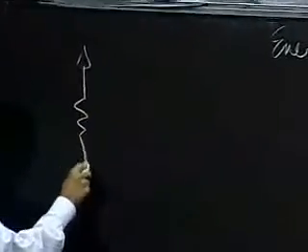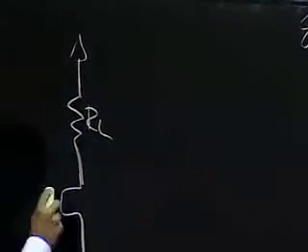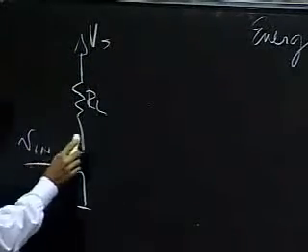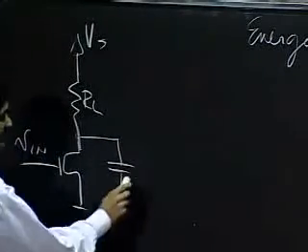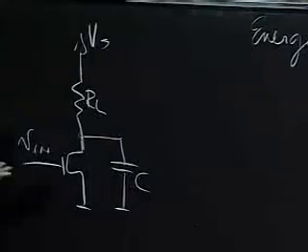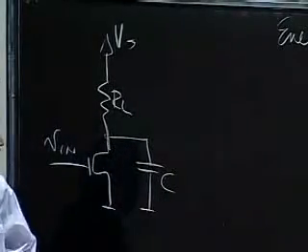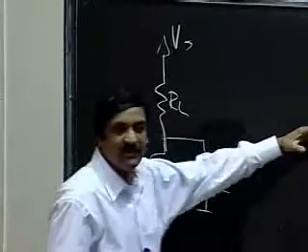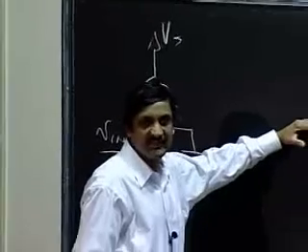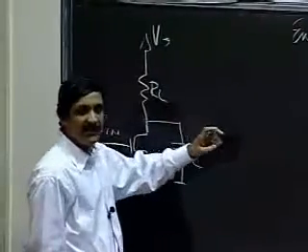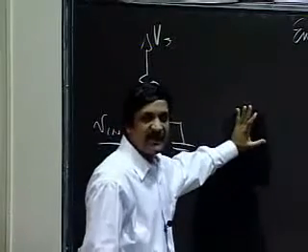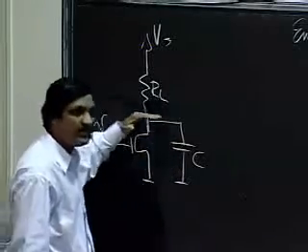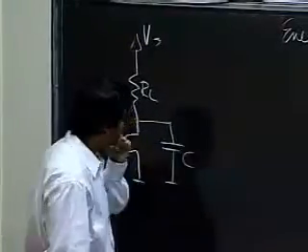What we saw last time was an inverter of this sort, Vs, Vn. And we said, let's study the situation where this inverter was driving a load capacitor C. Where did this load capacitor come from? Well, this inverter could be driving 1 or 2 or 3 or 4 other logic gates. So this C is the lumped value of the gate capacitances of all of those inverters. This may also include some component due to wiring capacitance.